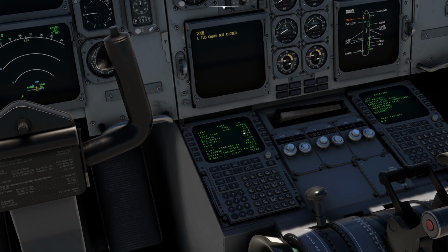And that's it. Now you have entered the initialization B page, which actually helps the plane to determine how much fuel it has and how much for the reserves and everything. Yeah, so this calculation is coming over here. For the taxi, 0.4 tons will be used. And the trip time is coming, how much fuel you have, how much time you have. And anything for the reserves, 0.2 and 5.0% for the reserves. And that's it.